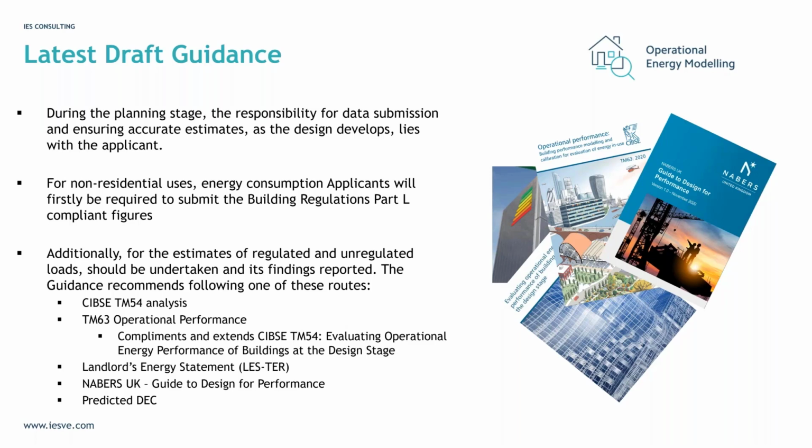As I say, the guidance on this policy is not finalised, but we understand that developers are encouraged to consider and implement additional best practice industry guidelines through an enhanced model, adopting the principles in guidance such as CIBSE TM54 and the recently issued TM60 series, relating to operational performance guidance, or perhaps the NABERS guidance will provide a suitable indicator of the building performance KPIs